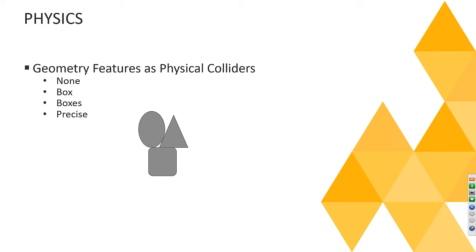When we have geometry in the component, not all of the component geometry needs to go to the physics calculation. Typically, some of your geometries are very detailed, and that would make the physical calculation very heavy and slow if you would throw all that detailed geometry for the physics engine to calculate.